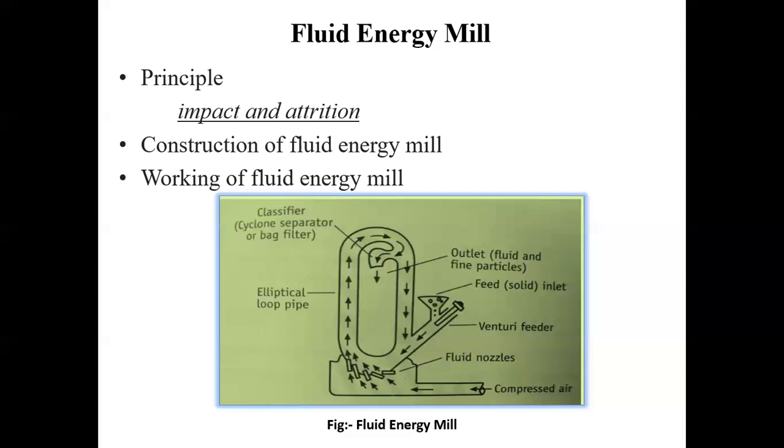Grinding nozzles, usually number 2 to 6, may be placed tangential and opposed to the initial flow path of the powder. Normally, compressed air of 600 kilopascal to 1 megapascal is used. Inert gases can be used to minimize or eliminate the oxidation of susceptible compounds.